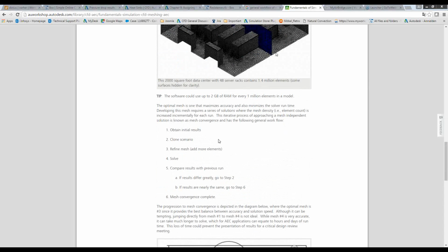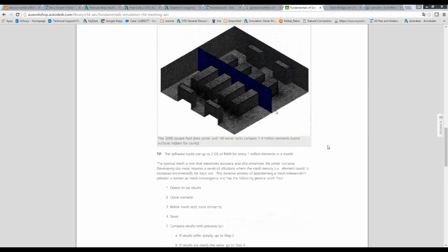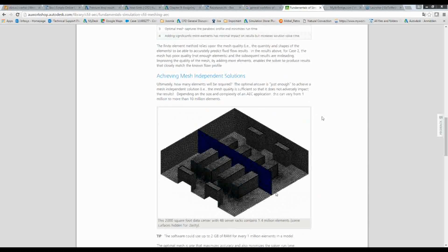If you think about it, because your fluid is moving, you're only going to be able to get the conduction at the near wall unless you're moving very slow. It's very velocity dependent, because you want to be able to get that heat to transfer all the way to the wall, and then it also affects what do you got?